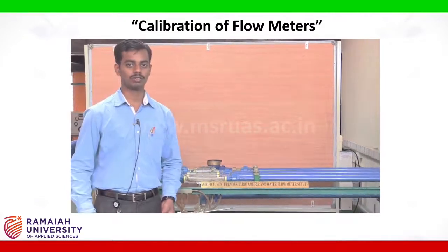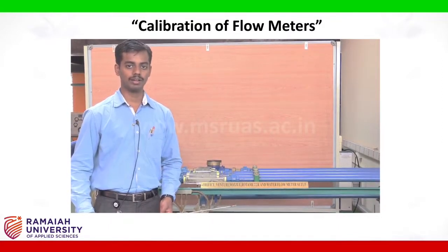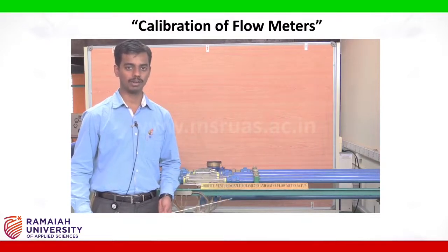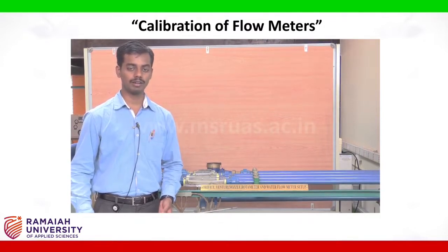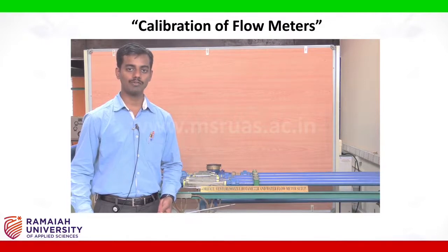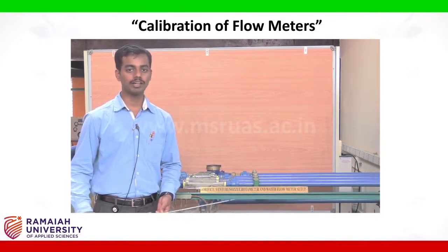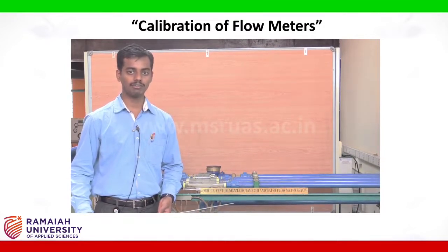We must know that the orifice meter and the nozzle meter are connected through the rotameter and not the venturometer. Hence, in the first stage, we calibrated the rotameter against the venturometer. Now, for the calibration of the orifice and the nozzle meters, we shall use the calibrated readings of the rotameter as the standard, and accordingly we shall calibrate the orifice and the nozzle meters.